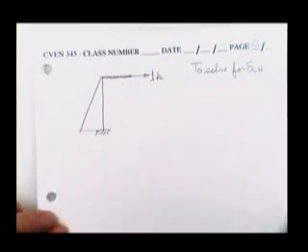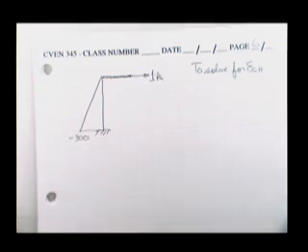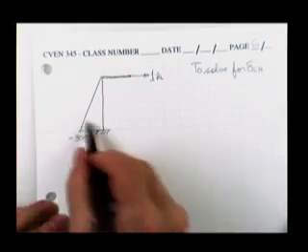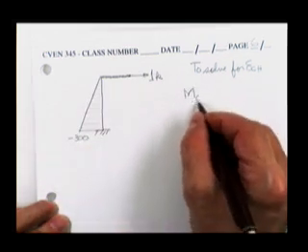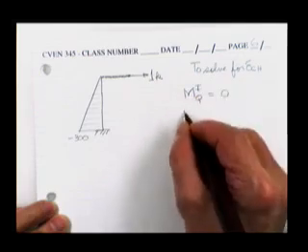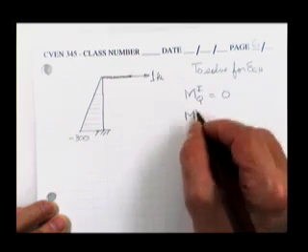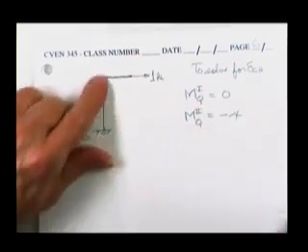So in other words, it just builds up linearly and is drawn on the tension side. It looks like this. And this would be a minus 300 because we decided that things drawn on the tension side, we call them minus for no reason. And I could write the equation for M due to the Q load in region 1 is equal to 0. And M due to the Q load in region 2 is equal to minus X. Just keeps on building up.